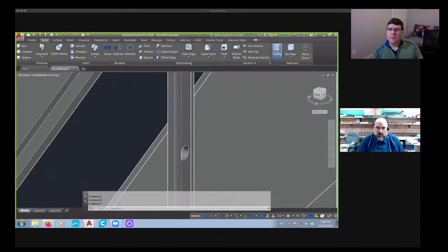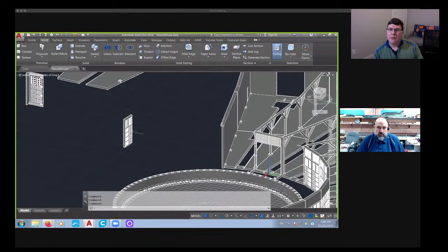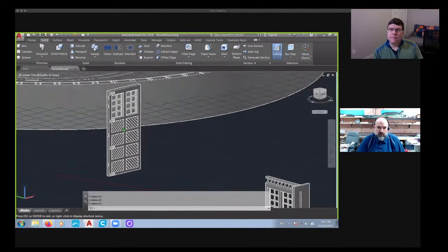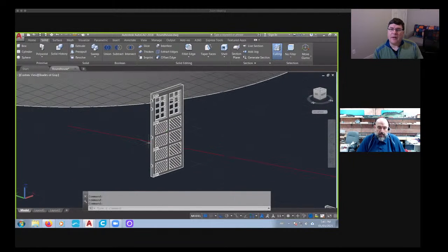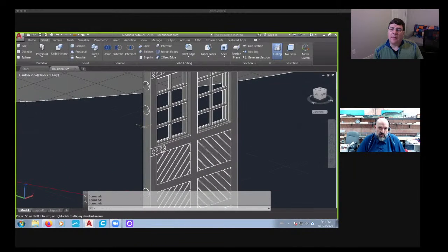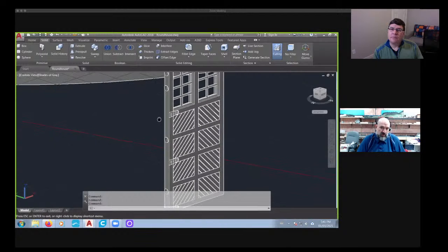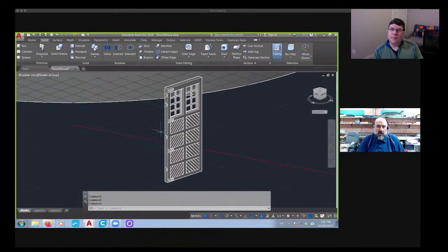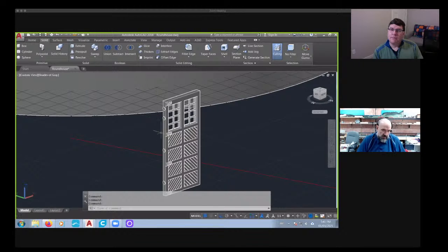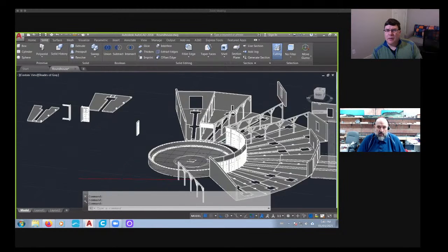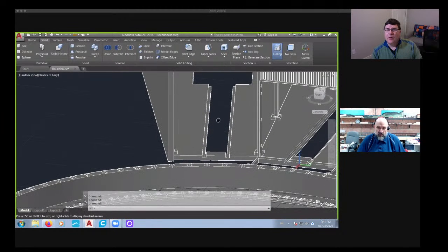And when I print out the door, I actually print it out at 99%. At 100%, there's actually expansion in the resin. And you can tell, the door is a little too big, and the holes just don't line up properly. And if you print it off at 98%, the door is too small, so 99 seems to be the sweet spot. But then I'm combining resin with FDM, right?